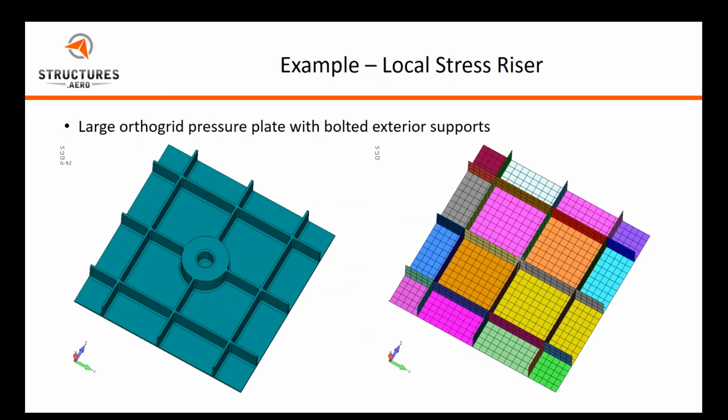So let's say you have a large orthogrid plate. I just modeled a small section here just for computation and modeling speed, so I could create the model. But you might model something like this. So you've got your orthogrid, and you just ignore these bosses with your interface, your bolts, and you might just throw an RBE in there with the C-bush. But obviously you need to know some more information later on, so you might use a breakout.